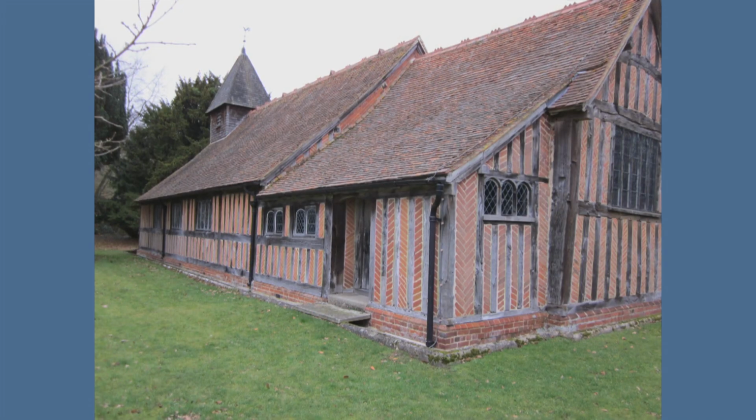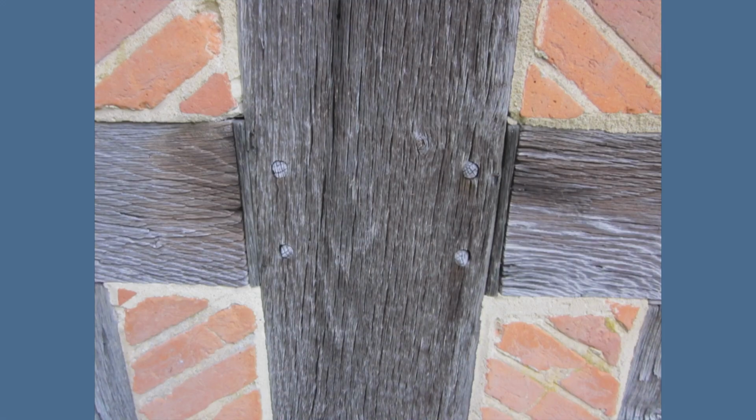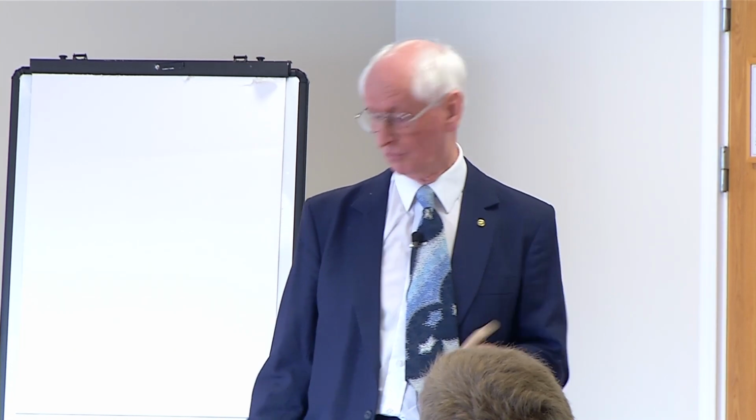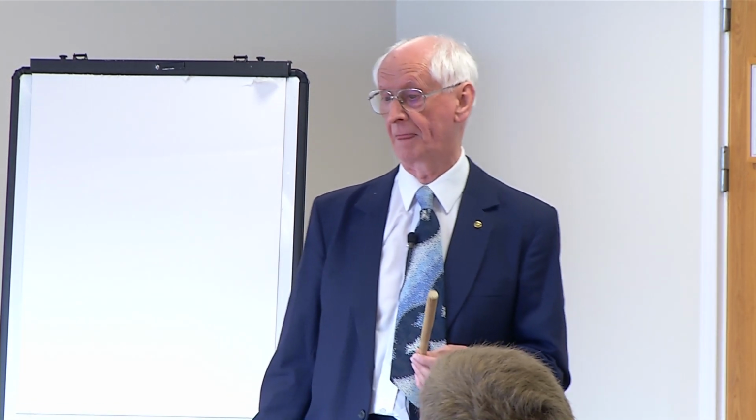And here is one, this is a very ancient one, to make my point about buildings which are historic. Very nice one. There's lots of brickwork in it, but it's only just filling the holes because it's basically a timber frame building. If you look at it closely, you can see the little pegs here and a nice bit of infill there where something has shrunk. And the timber's decaying a bit. There are cracks in it, but it's still there. It's still doing its job, and it will probably do it for another 100 years. And the structural fixings are all just wooden pegs.